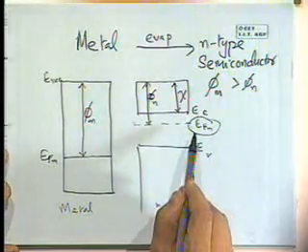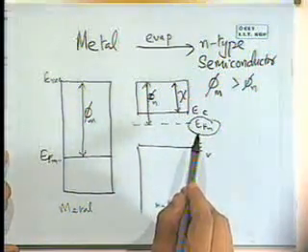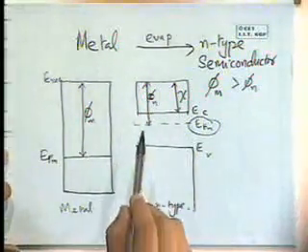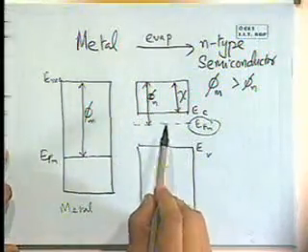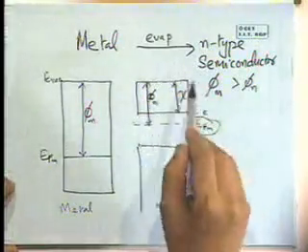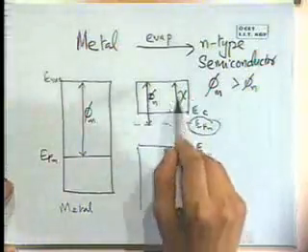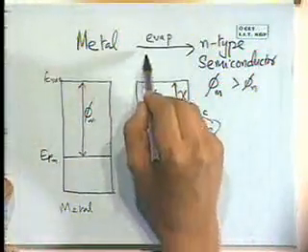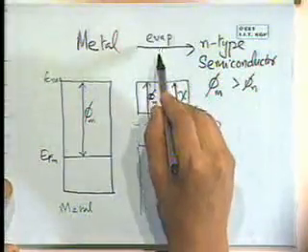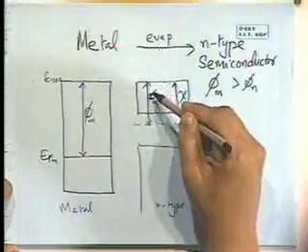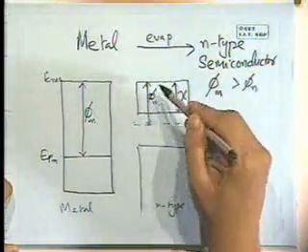Right? We have defined the work function, even in the case of the semiconductor, as from Fermi level to vacuum level. So even in this case, the definition still holds that is the minimum energy required to get the electrons out. The argument is a more detailed argument. It involves the fact that the semiconductor, if it's in thermal equilibrium, even though we are removing electrons from the bottom of the conduction band, in order to maintain equilibrium, some energy has to be absorbed to again bring back an electron excited from the valence band.